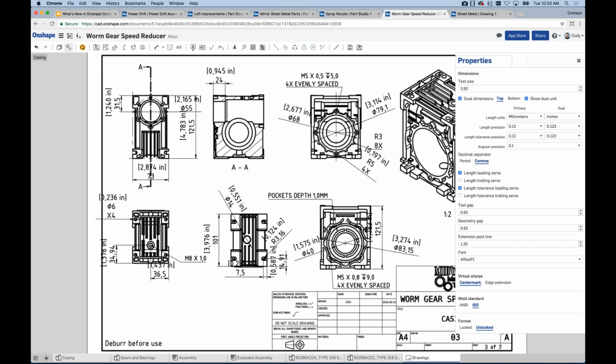Sometimes I exit out of sketches accidentally. Will restore work on sketches? Yes. In fact, the assembly behavior that I just showed you, that restore assembly, was mimicked after the behavior you get in a sketch. So for a long time now, you've had an option at the top to restore after canceling a sketch. So absolutely. That restore ability, we kind of took that from sketching and made it the same in assemblies.